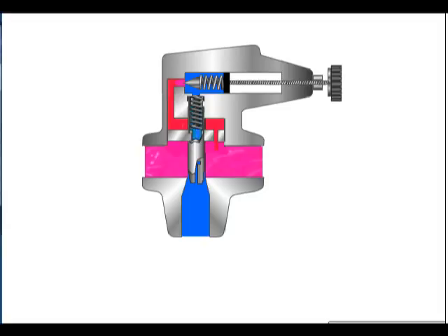This restricted flow caused by the orifice creates a pressure difference between the pump line and the area across the pilot orifice. This pressure imbalance causes the main poppet to move off its seat. This will discharge enough of the pump flow to prevent any further rise in the pump line pressure. When pump line pressure drops below the control knob setting, the pilot relief closes, flow through the orifice ceases, and the main spring can reseat the main poppet.